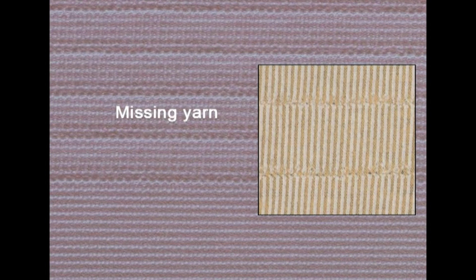And in case of missing yarn, that occurs in circular knits, caused by one end of yarn missing from the feed and the machine continuing to run. In woven fabrics, it is a yarn absent from a pattern, and sometimes it is treated as a minor or major, and we have even fabrics coming out with missed picks also, in the form of systematic patterns.